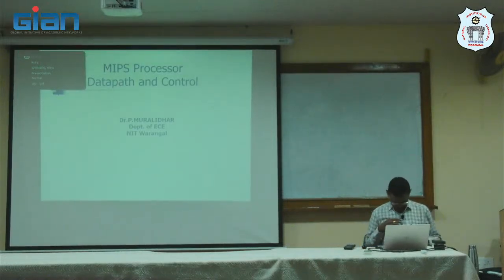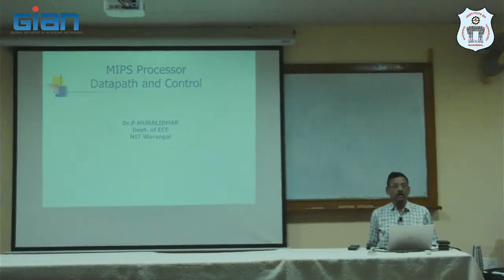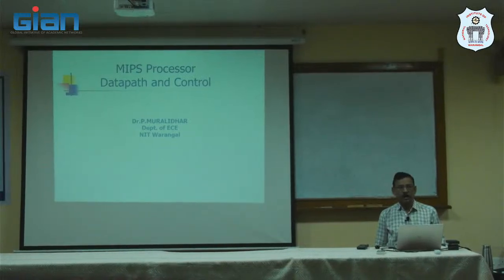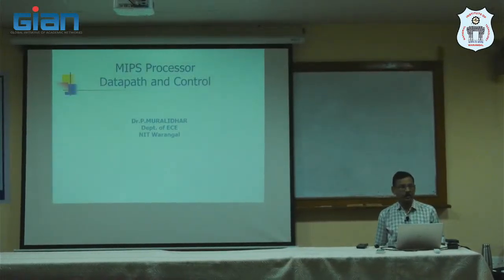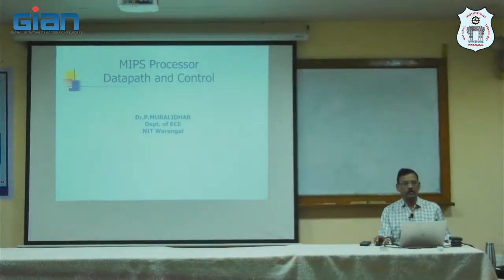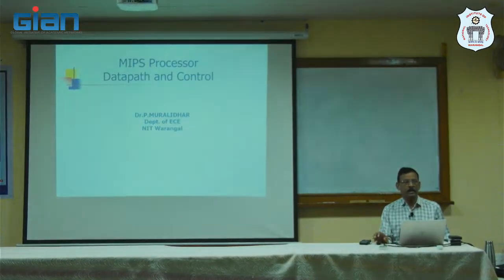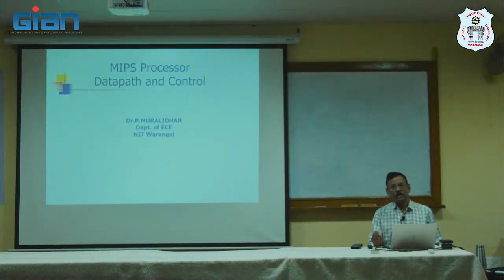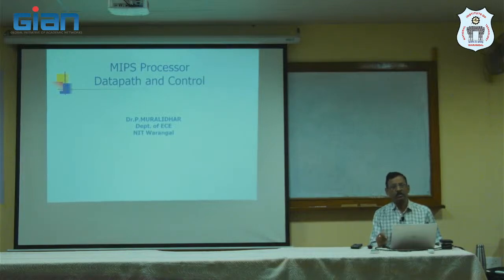Good morning, all. Today I am going to teach processor design, both data path and controller design. In complex digital systems, we can design the data path and controller separately, and later integrate both. In simple systems, both are designed together. But here, we first plan the data path components, then later the controller components.